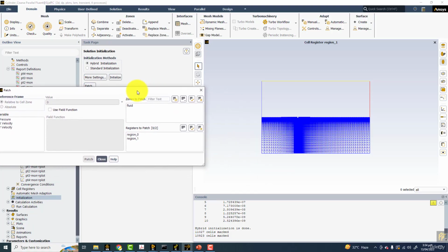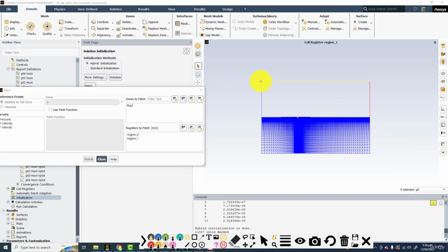So basically what I'm trying to do is that you know that the vortex shedding is basically the disturbance in the flow. Simple thing. The vortex shedding is the fluctuations in your average flow field. So that is behaving in this way. Some velocity is going down, then some velocity is going up. So if you provide disturbance by yourself in the initial field, the convergence to the transient flow will be faster.